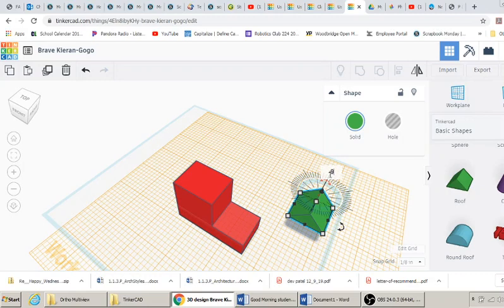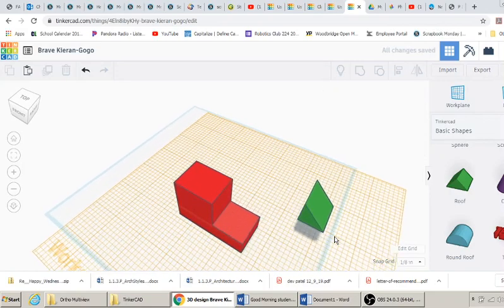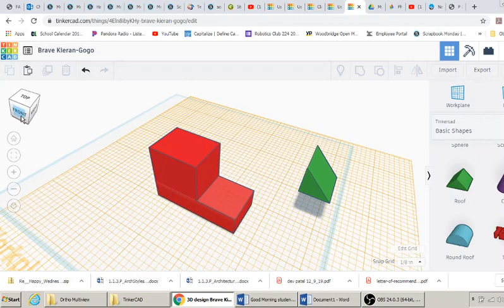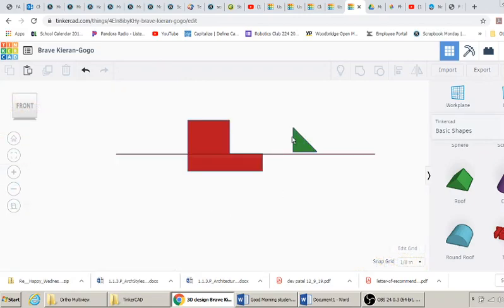Let me just start playing around with it. Okay, I want to drop it another 45 degrees. So -45 now, half that. There we go. It's flat. That's what I thought. So 90 and 45 is 135 degrees is what my intentions were rotating it. And as we could see, if I go to the front view, go back to ortho, there we go. We can see we're lined up.